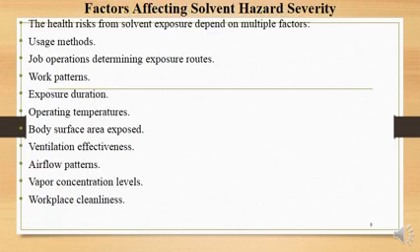Factors affecting solvent hazard severity. The health risks from solvent exposure depend on multiple factors: usage methods, job operation determining exposure route, work patterns, exposure duration, operating temperatures, body surface area exposed, ventilation effectiveness, airflow patterns, vapor concentration levels, then workplace cleanliness.